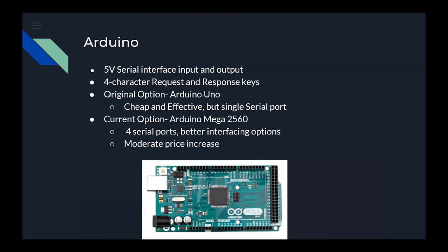Hello, I'm Gabriel Gomez, and I'll be discussing our Arduino signal generation and processing. Our data signal generation and processing is performed by an Arduino board using the 5-volt serial interface. Data transmission is performed in 4-character keys, broadcast in the 10-bit serial, start bit low, end bit high serial format